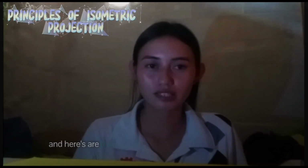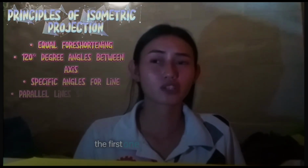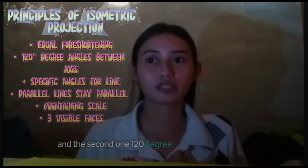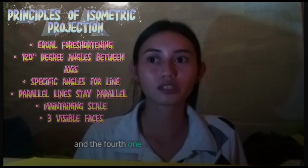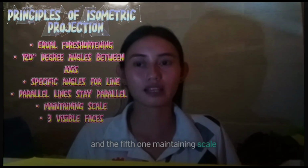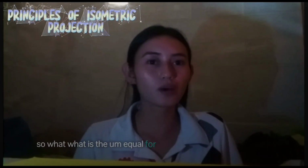Here are the key principles of isometric projections. First, equal foreshortening; second, 120-degree angles between axes; third, specific angles per line; fourth, parallel lines stay parallel; and fifth, maintaining scale. What is equal foreshortening?